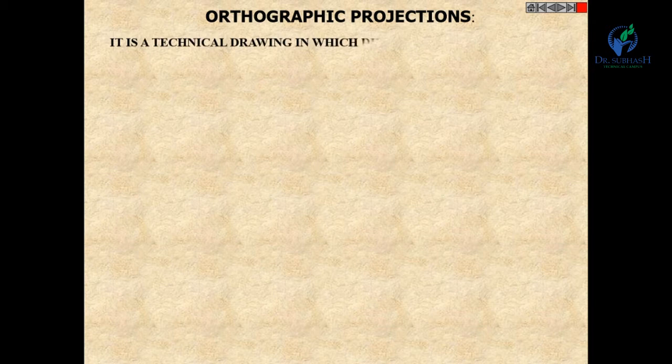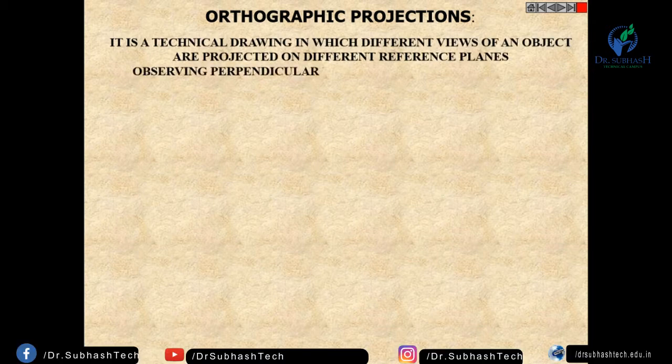Ortho means perpendicular. So it is a technical drawing in which different views of an object are projected on different reference planes, observing perpendicular to the respective reference planes.